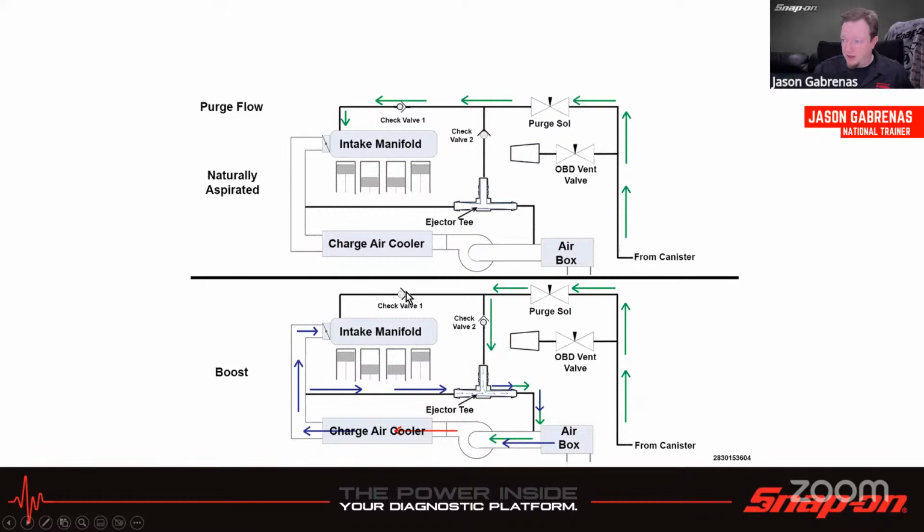So it's going to push that way and close that. Then it'll open this check valve here and allow it to go back through that T, through the air box, and then back into the intake manifold that way. So it just depends on what condition the vehicle is in. Is it under vacuum or is it under boost?